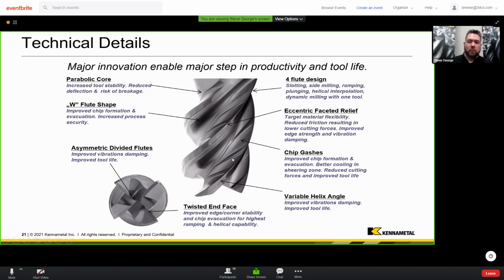So we go down about 25% in specific cutting energy typically with this tool compared to a normal 4-flute carbide end mill. What's really nice with this tool, in steel, we can go up to 2 times D slot, full slot. We've done 1 and 1.5 times D very easily in titanium and even Inconel, cast iron, lots of other materials.